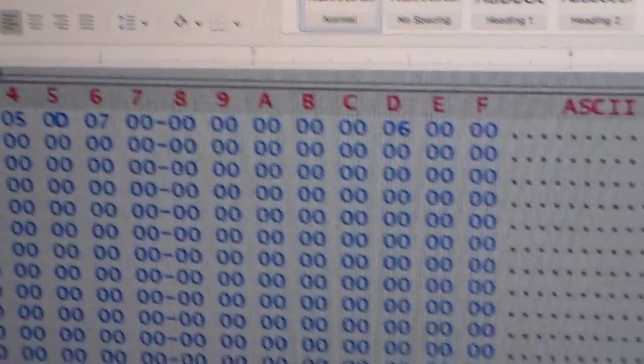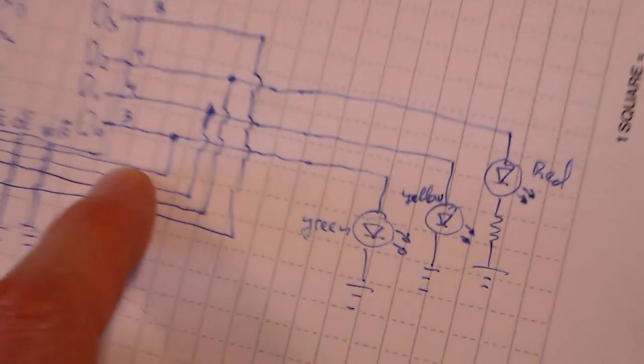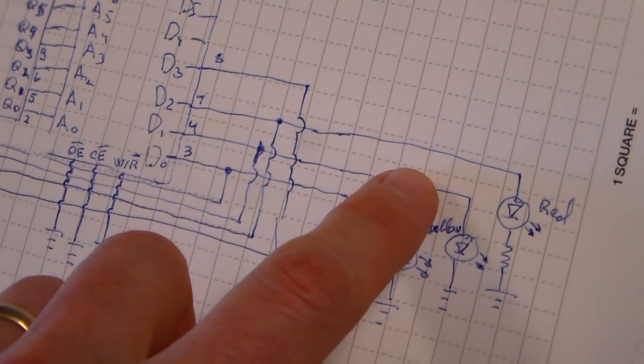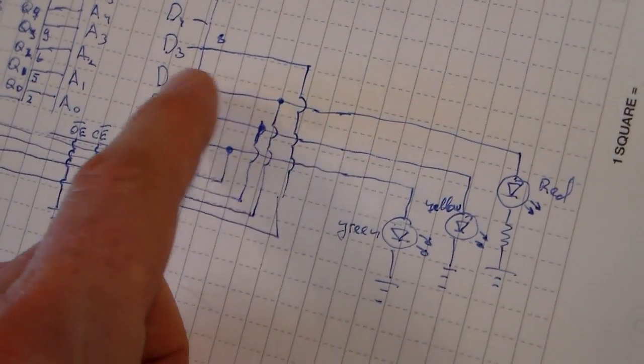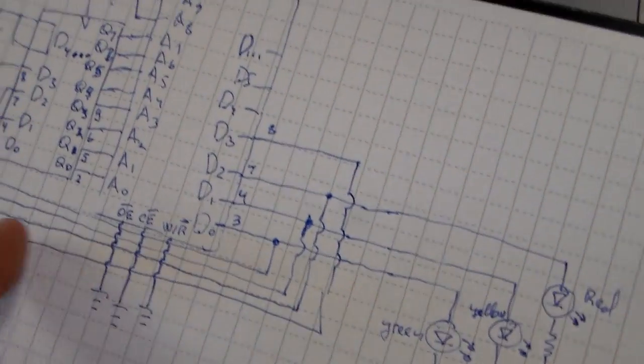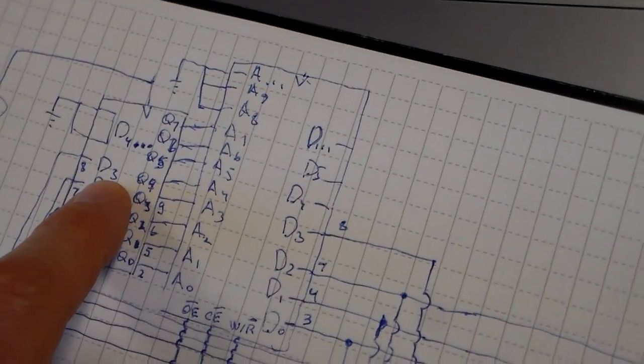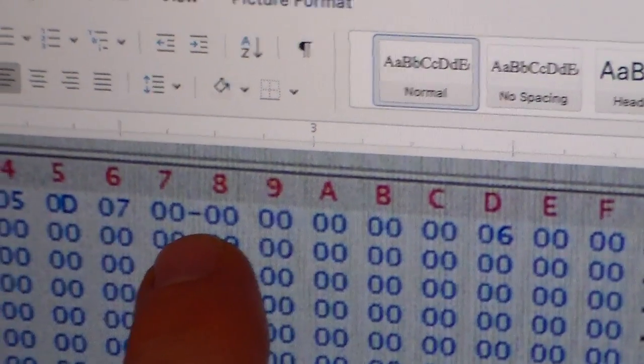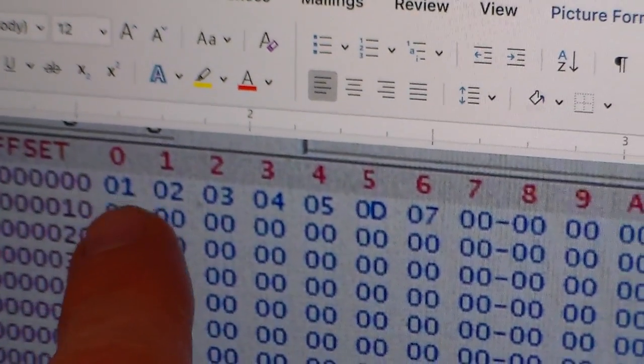And what that does is it basically outputs the lower 3 bits as a binary 5, but with an additional bit up here not connected to an LED, suddenly turns to a 1 to make the hexadecimal D. That feeds back around to give that 0D address. And then in the 0D address, it says, okay, here let's go to address number 6 next. We go back to 6, and we continue the sequence to 7. We go to 7, we go all the way back to 0, and we repeat.